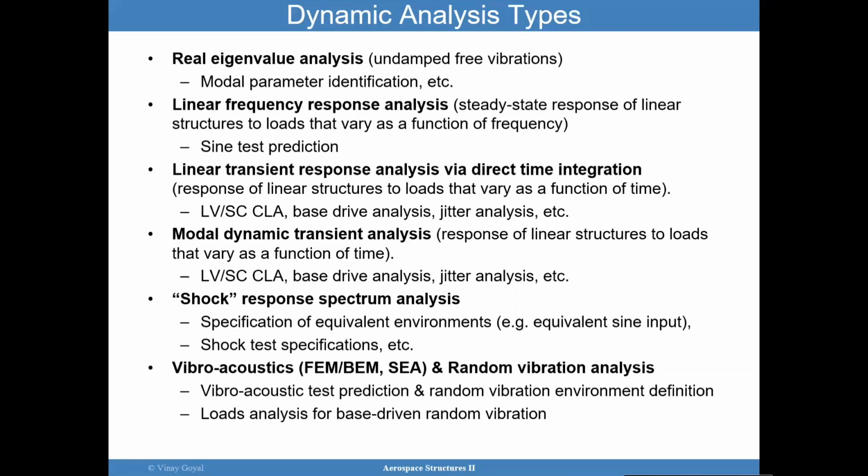You have the modal dynamic transient analysis, where you look at the response of linear structures to loads that vary also as a function of time. And you may use this approach to look at jitter analyses, base drive analyses, and coupled loads analysis, things that we'll be talking about later on. You also have a shock response analysis that can be performed, and then you have the vibroacoustic or random vibration analysis that can be conducted.